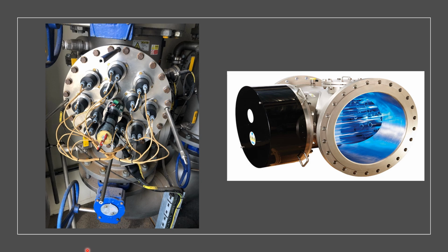Next we have a couple of pictures to show what the inside of each reactor actually looks like. On the left, you can see the 12 lamps arranged around the reactor head. In the center, there's an electric motor which drives an automated wiper system. This activates on a timer and sweeps the quartz thimbles every 6 hours. In this way, the thimbles are kept clean and free from debris.